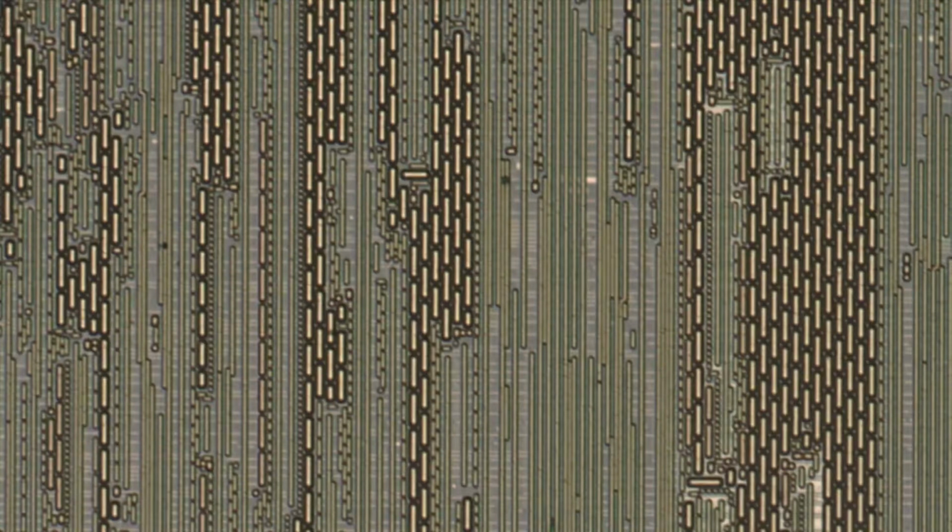Also, we can see a lot of these rectangular pieces of metal there, because any of the areas on the top layer that don't have metal, they filled in with filler to keep the chip well planarized. So areas on the chip that are the top layer of the chip that are empty are covered with metal like this. So we have actually not much access to the bottom of the chip without further deprocessing.